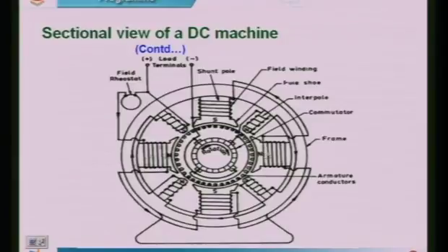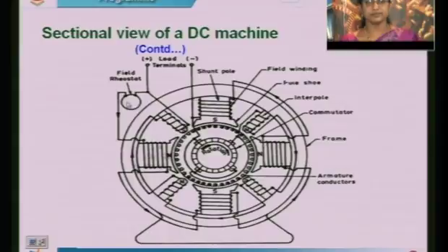See, this is how, when you are winding this magnetic field windings, and also when you are supplying by the external source. So, this is how the motor looks like. The constructional feature of both motor and generator is same. Interpoles, here one extra part is there, that is interpole. So, you are going to use this interpole to reduce the armature reaction effect.